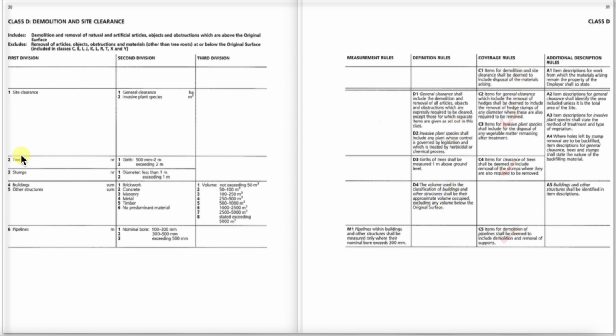They run across the page, so in site clearance we've got a horizontal line here and we've got a horizontal line here. So all of these, D1, D2, C2, C3s, A2, 3 and 4, all belong to site clearance between this boundary here. Now there is an exception in that when we look here, A4 seems to be a bit deeper.